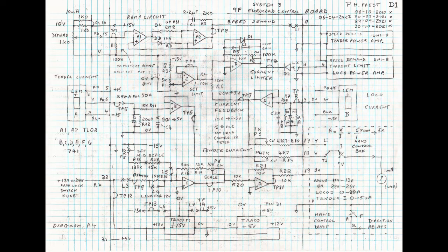The sharpness of this limit can be set via the op-amp D gain pot. The gain must not be set so high that instability occurs. Diode D1 avoids unnecessary excursion in the negative direction. The set point has been adjusted so that the current limiting starts progressively from 9 amps.